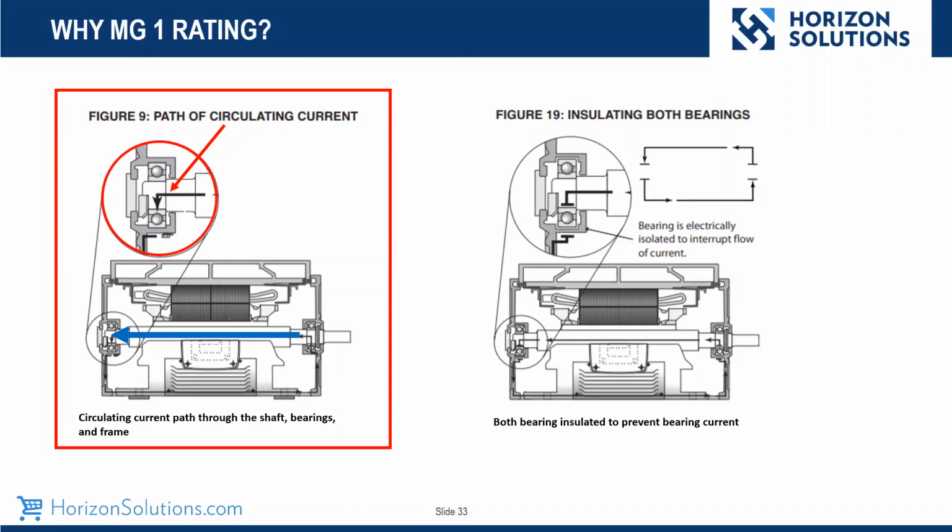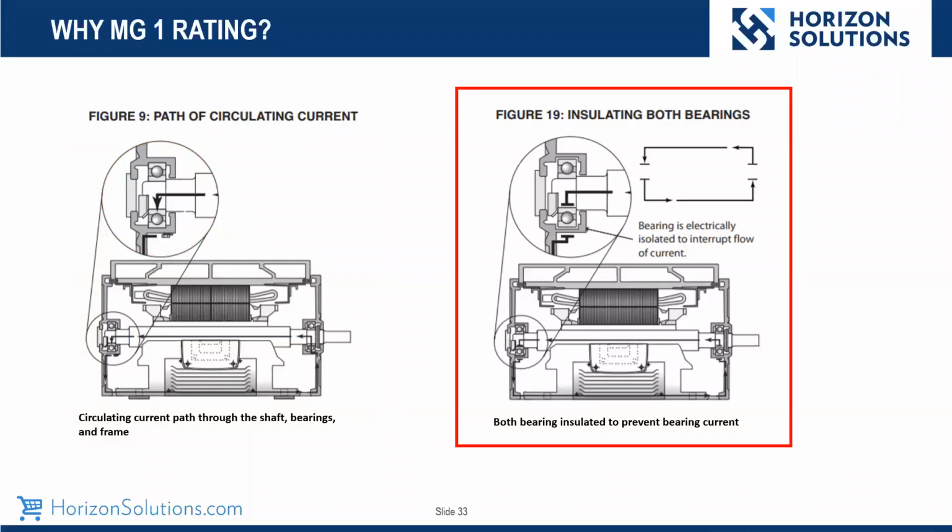Once again, these capacitive currents are seeking the drive where it was generated from. When you rectify off the distribution of 460 volts and you put it on a DC bus, you've now separated from that operating system or that distribution system. So now all the currents have to cancel to zero, and that happens at the DC bus. Next slide.